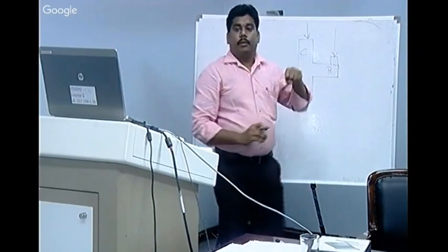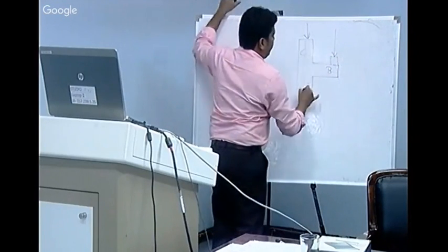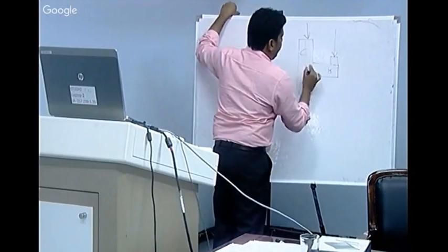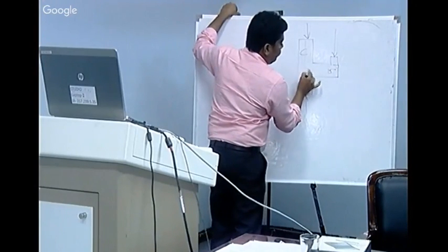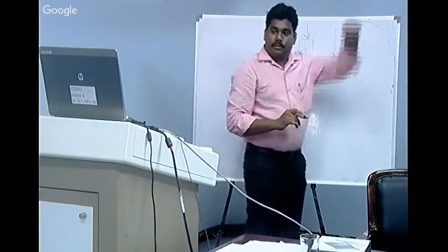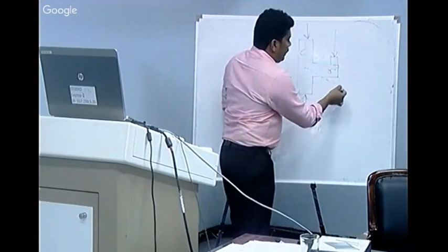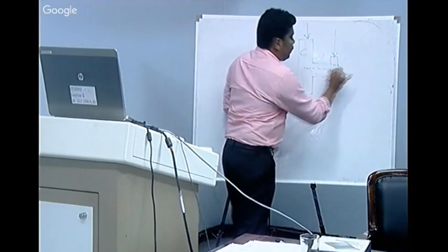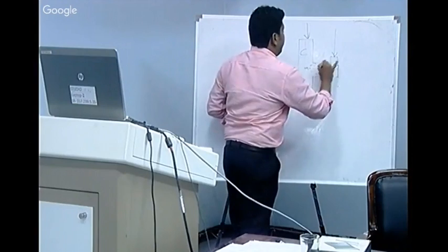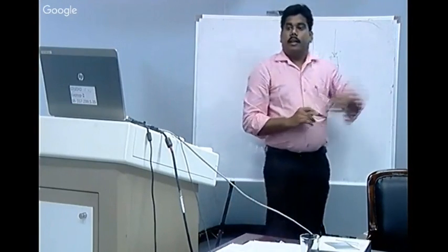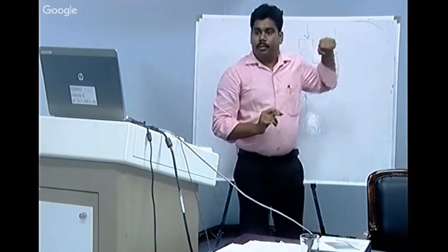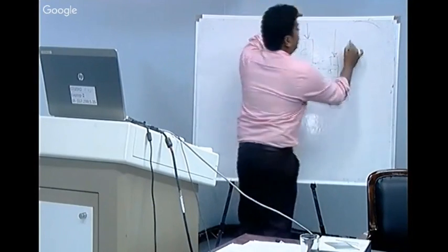This actuator will give you push, come to zero, then pull. So when you apply load, the beam will move like this. First, when you push, then when you pull, it will again come to the zero position, then it will move. Similarly, we apply this, which is called push and pull. This is called reverse cyclic load.